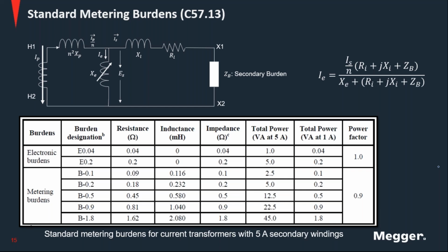The fault drove the CT to saturation, and when the CT came back out, given that the voltage applied to the secondary of the CT during normal operation is so low, because at nominal current you will be talking about only a few volts, there will be some amount of remnant flux in the transformer. That can increase the excitation current on the transformer.